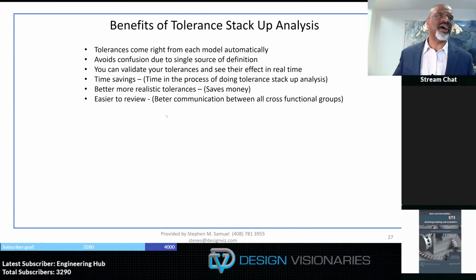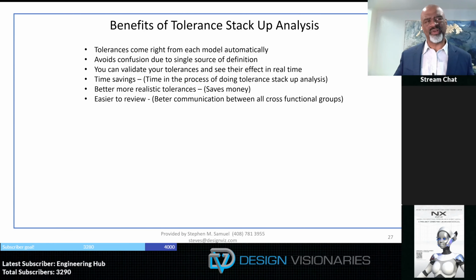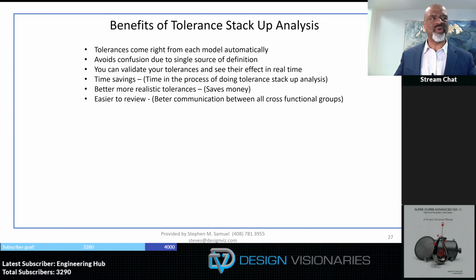But with the ability to put PMI, product manufacturing information, on individual models and all of the GD&T callouts semantically on surfaces, and when I use the term semantically, what I mean is these callouts are placed on the model in such a way that there's knowledge of the actual surfaces and what they would do on the actual surfaces themselves, not a representation of the surface.